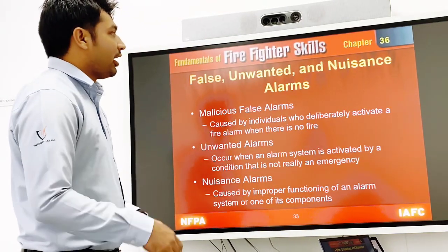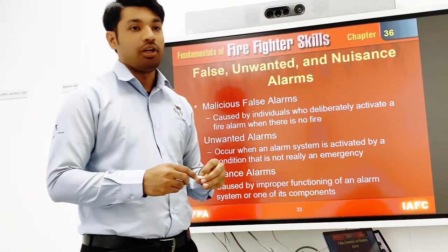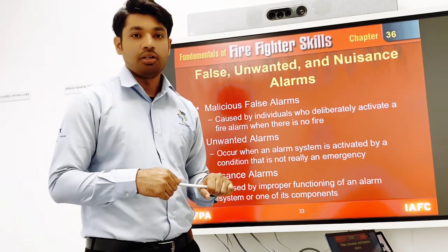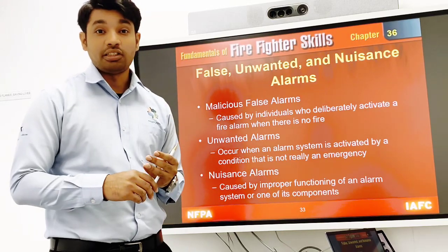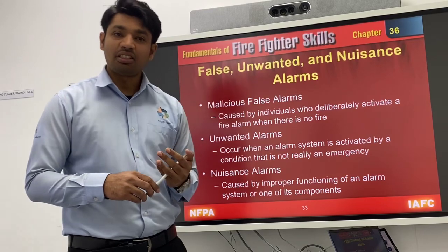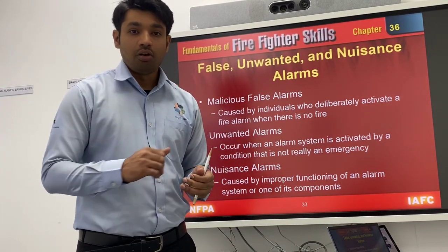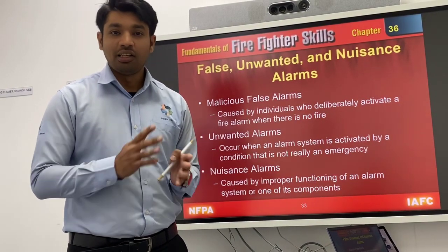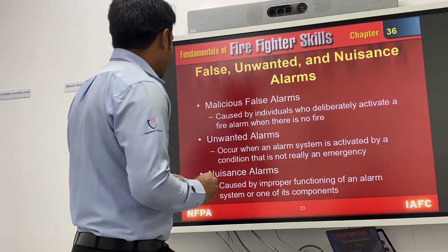False, unwanted and nuisance alarms. There is always a big problem when we are dealing with fire alarms. Mostly alarms are fake. In a 2017 NFPA study, 67% of alarms in communities were fake, because smoke detectors are very sensitive. If someone is using a shower, doing laundry, or using some spray, it will be triggered. So how to avoid these false alarms, we can discuss now.